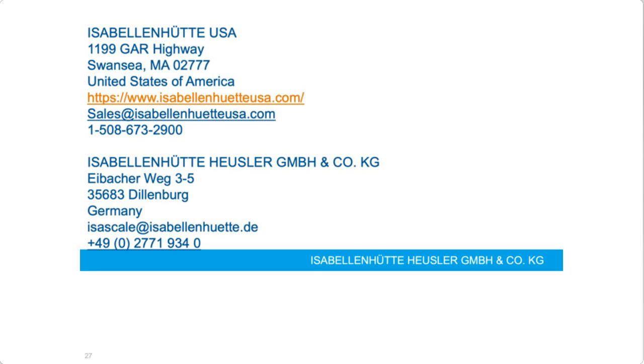But if we talk about DC fast charging, the DC fast chargers usually have an isolation monitoring system. So in that case, the charging station system can interfere with the vehicle's isolation monitor. So the vehicle's isolation monitor should be disabled during charging. I have to say, though, this has to be evaluated case by case and based on the system that is used. So you really have to look at that system by system.